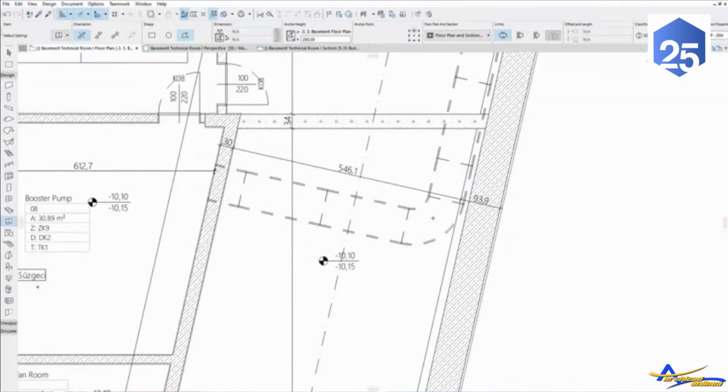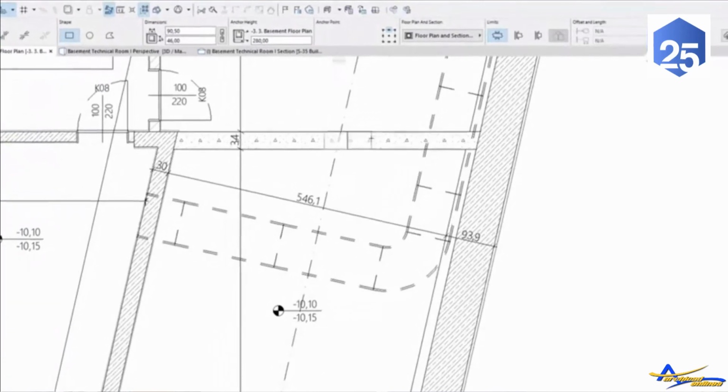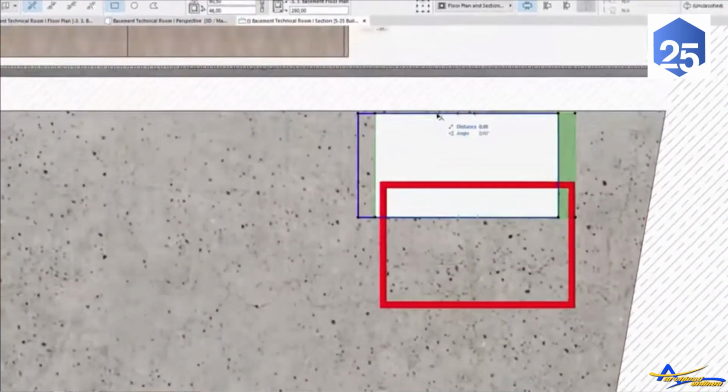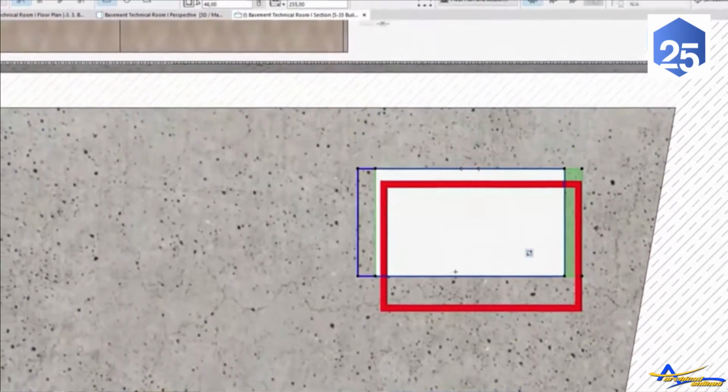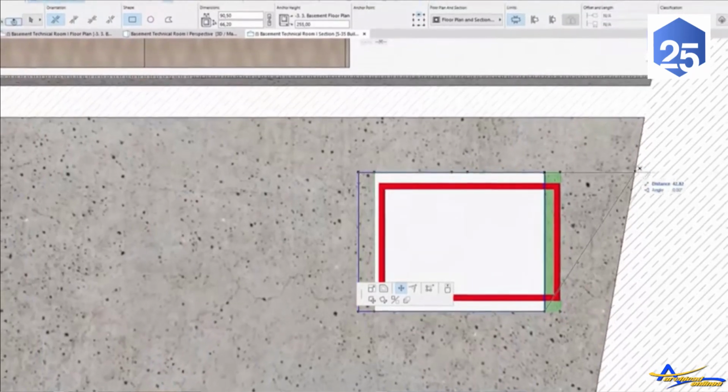Convert existing rectangular and circular geometries into polygonal shapes by using flexible editing options. Let's cut a rectangular opening into this structural wall on the floor plan view. Then modify it for accuracy in 3D or in the section view and change the geometry for the specific needs.